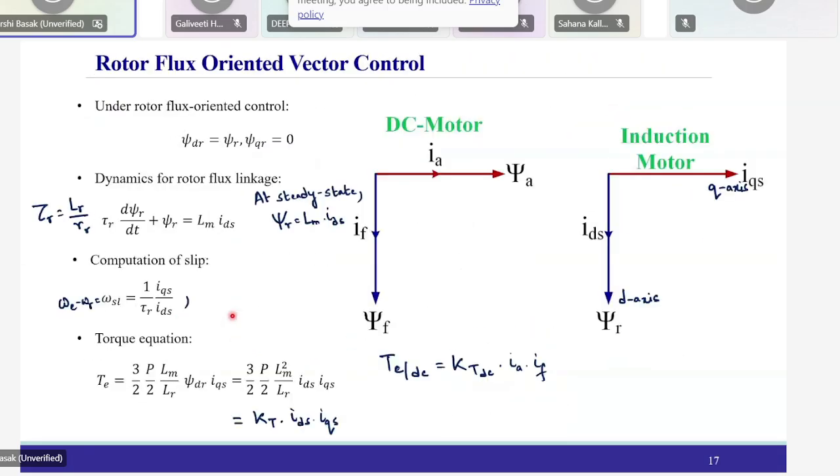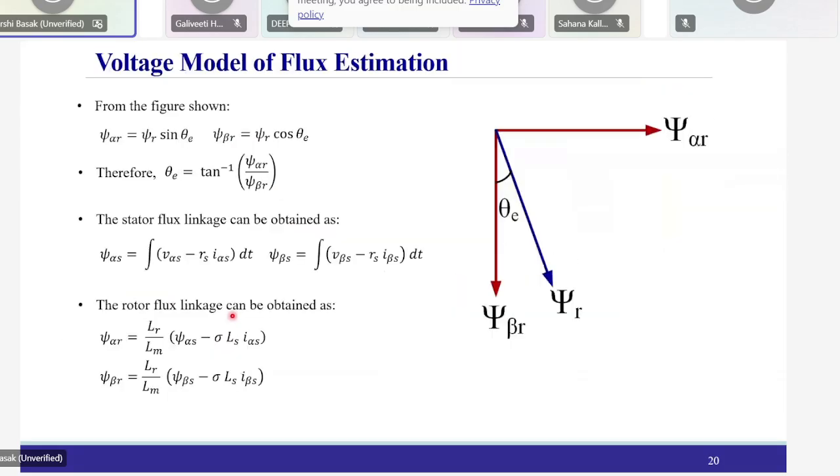The rotor flux is also a rotating vector, rotating in synchronicity with your stator field, and both of them should rotate at the same speed to produce effective torque. Otherwise, effective torque will not be produced. The average torque will become zero otherwise.